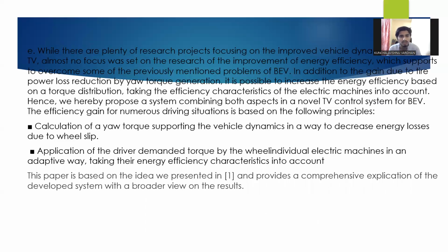While there are plenty of research projects focusing on improved vehicle dynamics, almost no focus was set on research into the improvement of energy efficiency, which supports overcoming some of the previously mentioned problems of battery electric vehicles. In addition to the gain due to tire power loss reduction by yaw torque generation, it is possible to increase the energy efficiency based on a torque distribution, taking the efficiency characteristics of the electric machine into account.